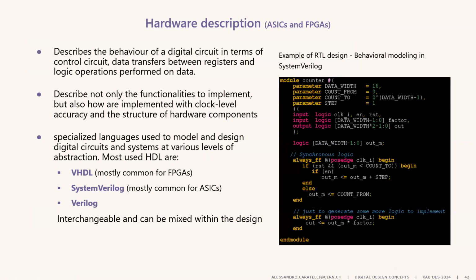So here you describe the behavior of the digital circuit in terms of control circuit, data transfer, logic operation, and so on. And you describe not only the functionalities to implement, but also how these functionalities are implemented with clock-level accuracy and the structure of the hardware components. And here you use specialized languages like VHDL, SystemVerilog, and Verilog. Here you have an example of a counter, an example of RTL design, behavioral modeling in SystemVerilog.